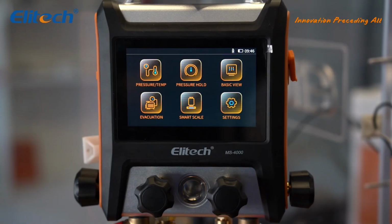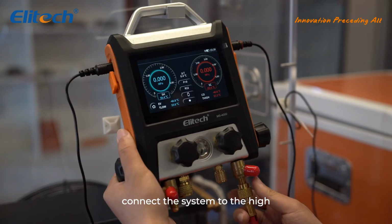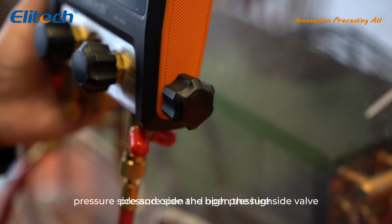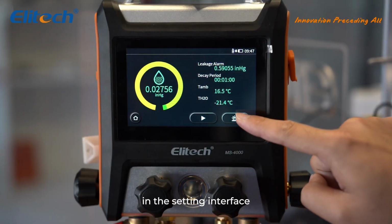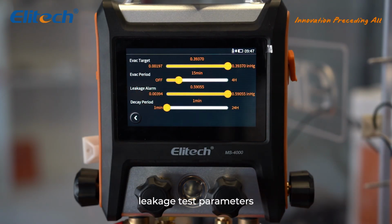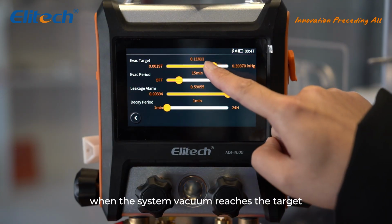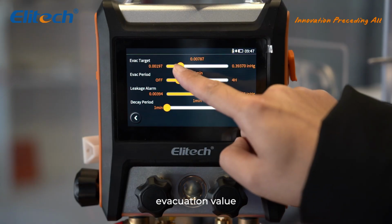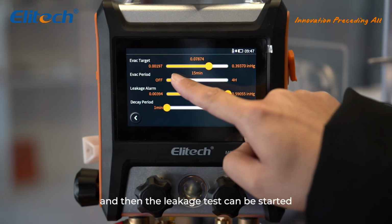Vacuum test. Click Vacuum test on the main interface to enter the vacuum function. Connect the system to the high pressure side and open the high pressure side valve. In the setting interface, click Vacuum settings to set the leakage test parameters. Target evacuation value: when the system vacuum reaches the target evacuation value, the device alarms, and then the leakage test can be started.